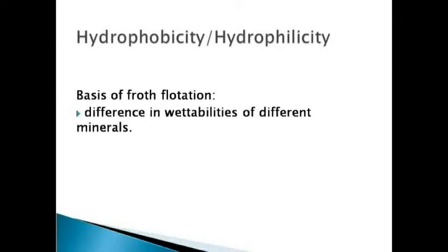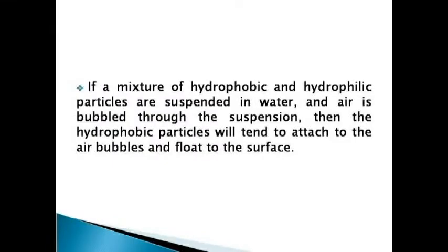The basis of froth flotation is the difference in wettabilities of different minerals. Particles range from those that are easily wettable by water, hydrophilic, to those that are water repellent, hydrophobic. If a mixture of hydrophobic and hydrophilic particles are suspended in water and air is bubbled through the suspension, then the hydrophobic particles will tend to attach to the air bubbles and float to the surface as shown in Figure 1.